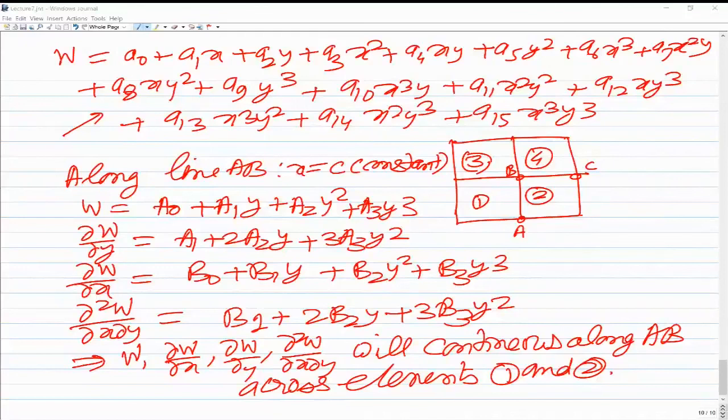Because the primary variable and subsequent secondary variable cannot be defined at the same point. Yes, the corresponding secondary variable cannot be defined. So that is the difficulty. If we have only primary variables as degrees of freedom, then it is easy to give the boundary condition. But if the secondary variables are involved, then defining the boundary condition becomes a difficult task. Usually, what we do is specify only the primary variables and leave the secondary variables as unknown.